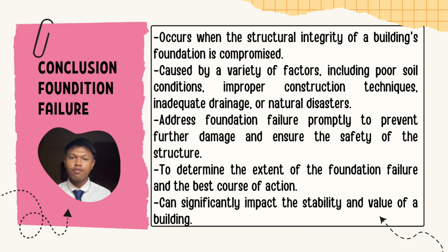Next is conclusion, foundation failure. Foundation failure occurs when the structural integrity of a building foundation is compromised, resulting in various issues such as cracks in walls, leaning walls, collapsed walls, and other structural problems. This failure can be caused by a variety of factors, including poor soil conditions, improper construction technique, or natural disaster. It is crucial to address foundation failure promptly to prevent further damage and ensure the safety of the structure.